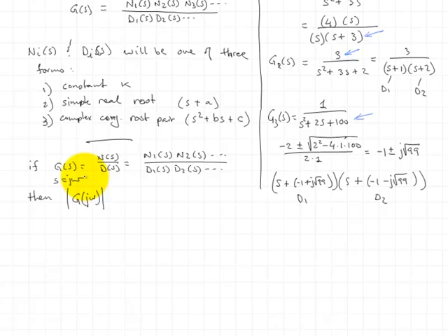However you get to it, eventually you're going to have this transfer function that is a function of s. But when we talk about frequency response plots, we are restricting ourselves to the case where we are exciting the real system with real sinusoidal signals, like sine omega t's, cosine omega t's. And in that case, those type of signals are constructed by e to the j omega t.